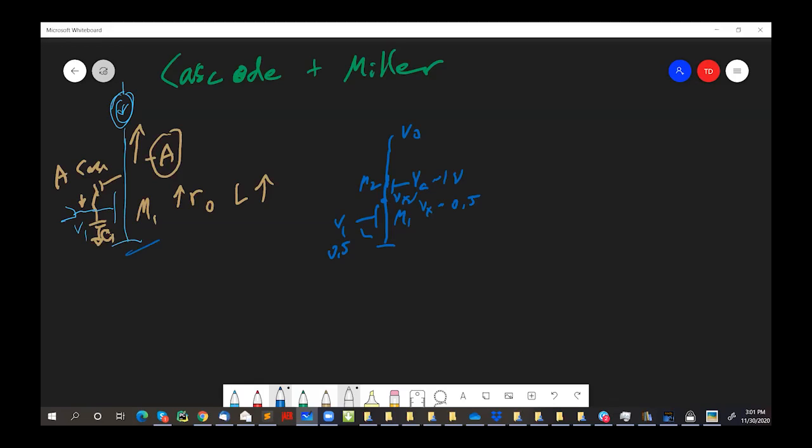This is a very cool trick because this top transistor here kind of shields it like a waterfall. It kind of shields the drain of the bottom transistor. It increases the apparent drain resistance looking into VO by the intrinsic voltage gain of the top transistor. And I'm going to calculate that for you now so you can see the calculation one time. But the intuition is that it kind of shields it. And so now the drain of this bottom transistor moves a lot less than it did before. And since it moves a lot less when you move VO, it increases the apparent drain resistance by a huge factor, say a factor of 100, quite easily.